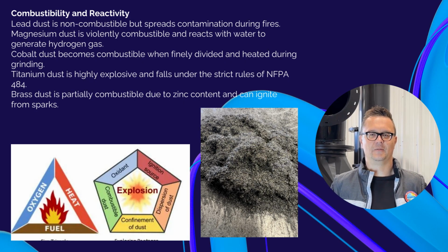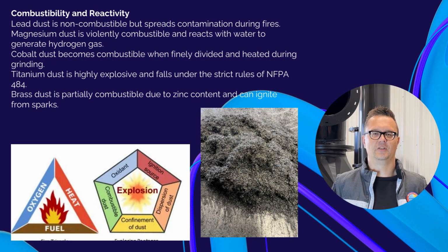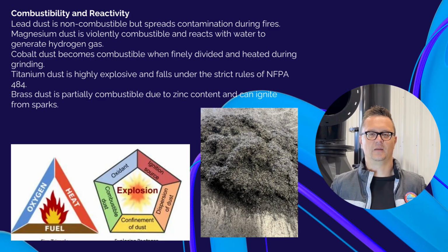Combustibility and reactivity. Not all metal dusts burn, but the ones that do are extremely dangerous. Lead dust is non-combustible but spreads contamination during fires. Magnesium dust is violently combustible and reacts with water to generate hydrogen gas. Cobalt dust becomes combustible when finely divided and heated during grinding. Titanium dust is highly explosive and falls under the strict rules of NFPA 484. Brass dust is partially combustible due to zinc content and can ignite from sparks. Magnesium and titanium are the most reactive, while lead is the least, but every metal requires control.